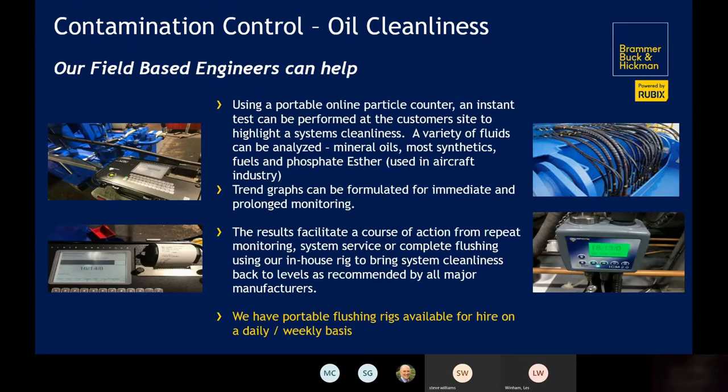So if action is required, either an oil change may be suitable, or a simple flushing rig may allow us to filter the oil and bring it back up to the correct standard. The unit works by creating a closed circuit in your hydraulic system and forces the oil around turbulently at high pressure, picking up debris and contaminants, where the high-end filtration system then filters out.